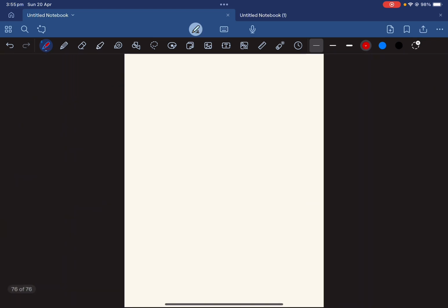And then the third one is going to be internal balance. In case of internal balance, it's the same as inside hinge, I'll just write it down. It's nothing different, same as inside hinge, but inside the wing. So basically nothing is coming out of the wing that you could see. Alright, so these were the ways how you would reduce your hinge movement.